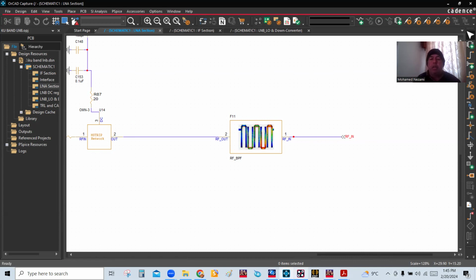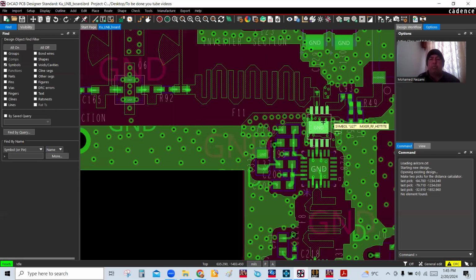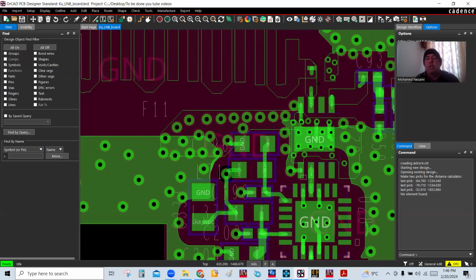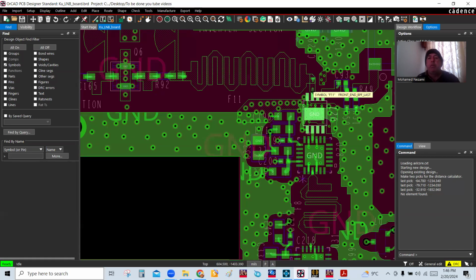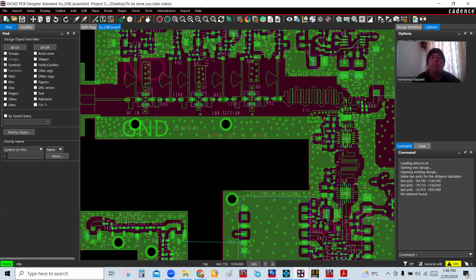And once you do that, the PCB designer also comes in, and in this case, I was the RF designer and the PCB designer for this client. The PCB designer adds all this copper pouring, all these vias, all these extensions to extend the signal, the transitions, the 90-degree bends, the mitered 90-degree bends, and so forth. We add all of these so that we can get the signal through and make a PCB out of it, and something might go wrong.